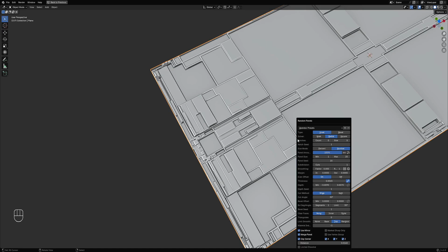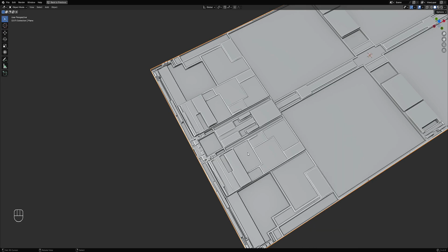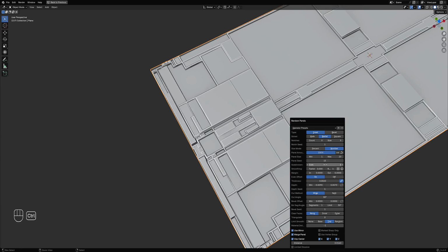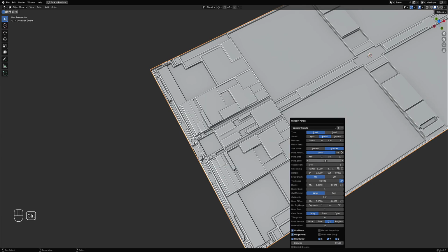It is much easier to repair the topology by doing the design first instead of modeling and fixing the topology at the same time. You're going to waste more time doing that than just focusing on the design first, then going to the topology and repairing it. Since this is mostly angular, it's really easy to lower its topology. 0.001.